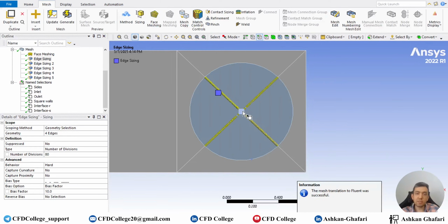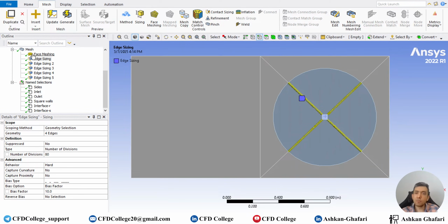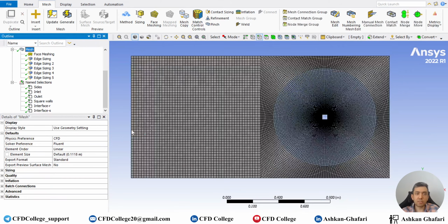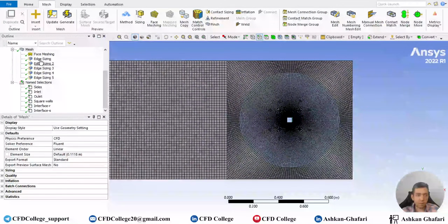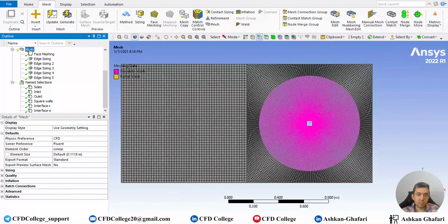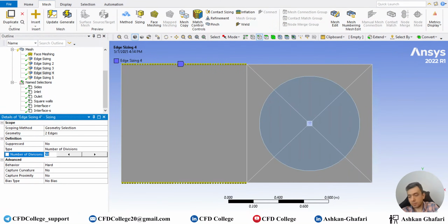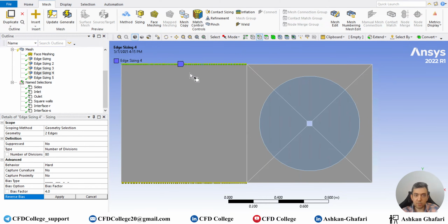Since the flow is turbulent, you have to check Y plus. You can see my video about checking the Y plus in CFD simulations in ANSYS. Okay, let's increase it a bit. And also this should be 80. And we can use bias factor of, for example, 4. I should reverse the bias for this one.